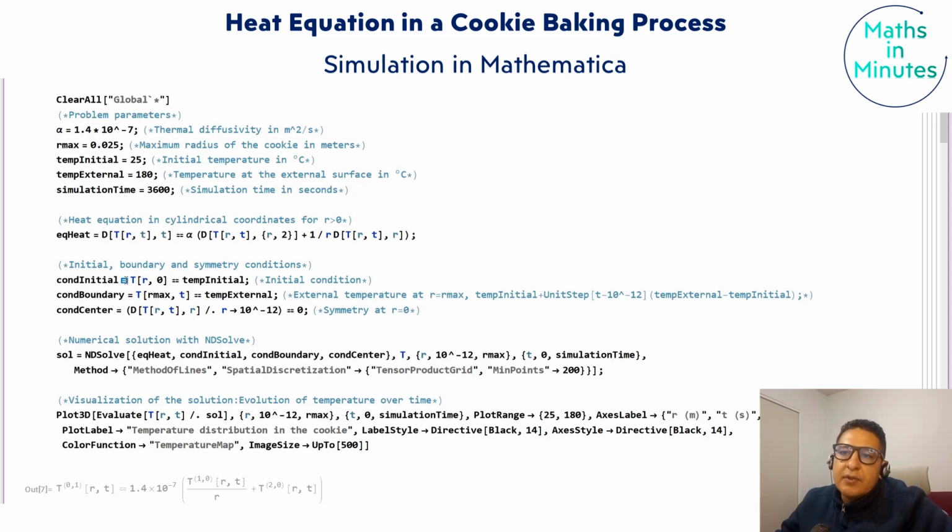This is the difference between this one and this other, okay? So after that, coming back to the NDSolve function, we have to write the equation and the conditions. After a comma, we have to write the temperature, because this is our dependent variable. And finally, as this is a numerical solver, we have to write the interval in which the integration will be performed.